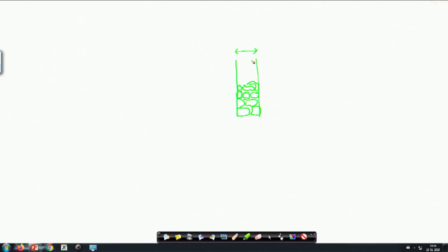So, to achieve this thickness, maybe a few stones have been set together, but it has to be remembered that after some layer there should be a continuous stone to support it, not to allow it to break in this direction.